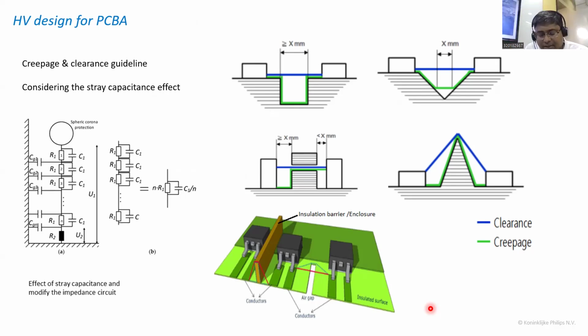Yeah. On the DC side boards, we have to use those high frequency creepage guidelines, and every industry basically has its own guideline. It's not anymore like an IEC standard that I follow. Here mainly it is the different companies, GE, Siemens, Philips, who have their own guidelines. So on the AC side, those things matter. And when it gets rectified on the DC side, because the DC side also has a lot of measurement circuits, we follow a different guideline which is applicable for the DC side.